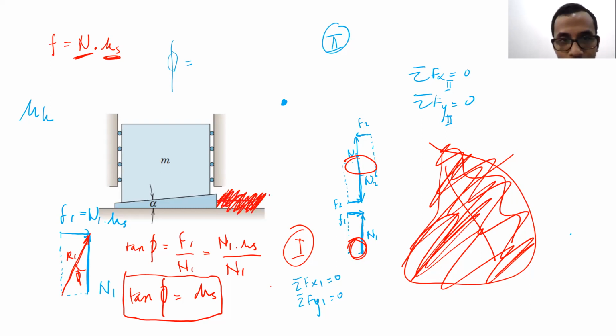So you delete that force P. A self-locking wedge means that after it's pushed in like this, when the force P is gone, the wedge will not be able to move by itself. So the wedge will stay there. If the wedge is staying there, then we can say that the wedge is self-locked.